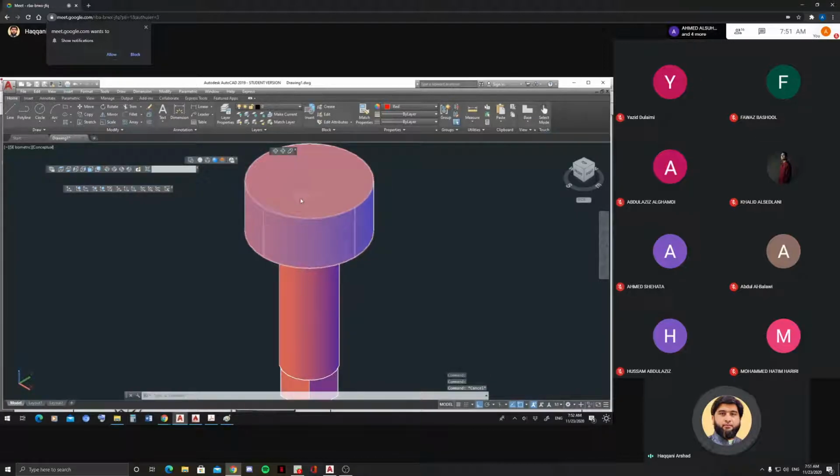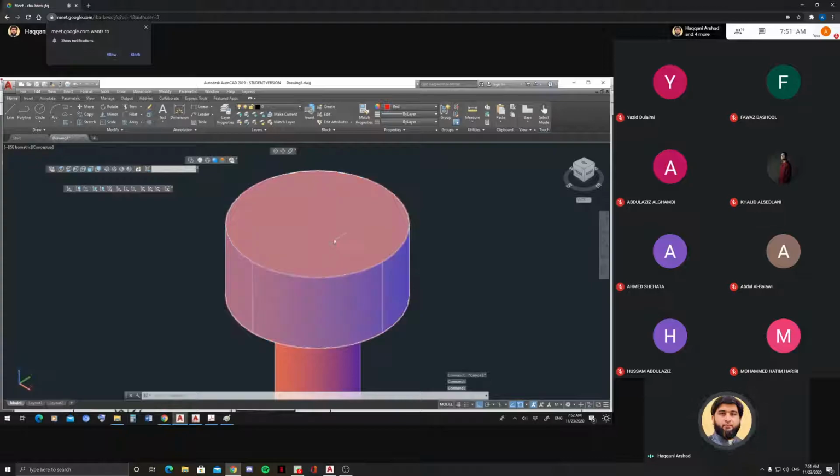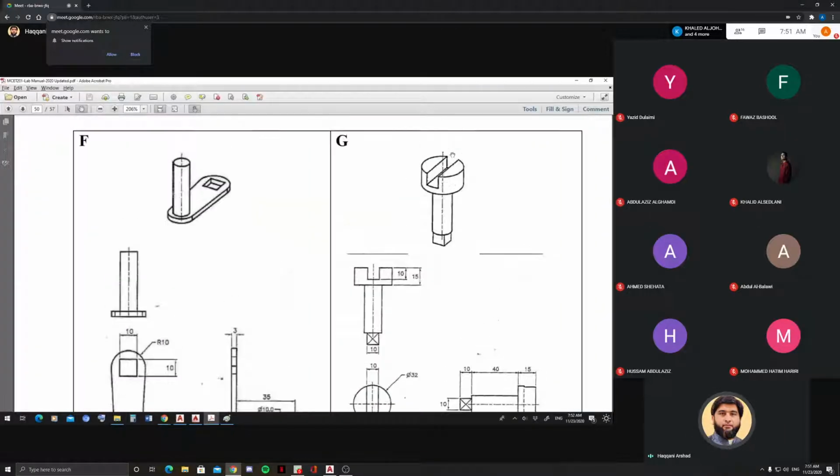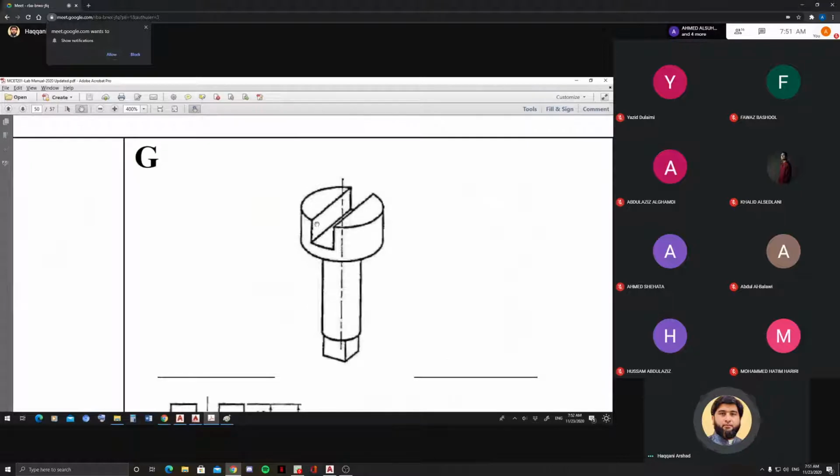Now to this bigger cylinder there is a slot. There is a slot of 10 thickness. So for that I need to draw another circle because I need to draw a slot. I cannot directly draw two lines. If you see this shape and then cut it, the same thing we are going to do is draw this slot and then extrude it and then subtract. So this will be removed. You can easily cut. So when you are talking about cutting, you do subtract.